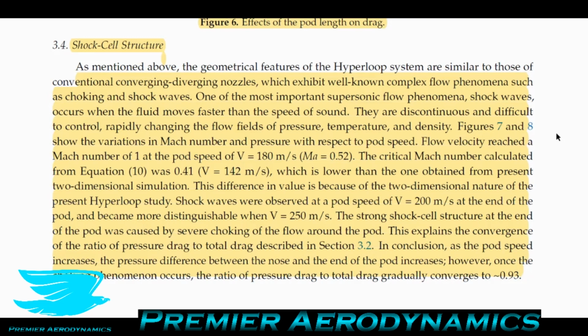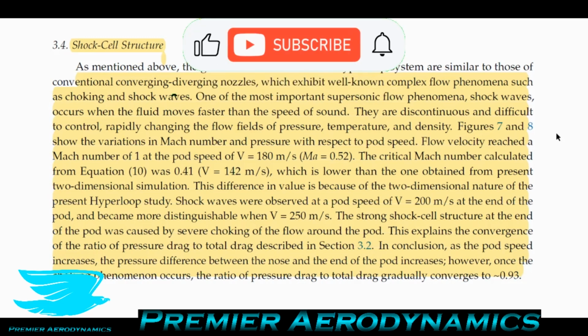That's really bad. Like if you were to design an airfoil with the Mach number of that, or an airplane, that'd be terrible. And really, streamlined bodies, you're not going to get a critical Mach number that low. Usually they're going to be above 0.8 or so. So really only bluff bodies, you're going to get critical Mach numbers this low.